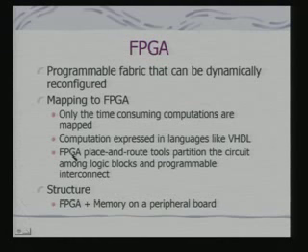But the issue now turns out to be that you have expressed your computation, but that computation has to be mapped among the logic blocks of the FPGA, because FPGA, as we said, is a programmable fabric. In a sense, it contains a set of programmable modules. We shall see examples of those soon, but let us try to understand what FPGAs are right now conceptually. There will be a set of logic blocks.